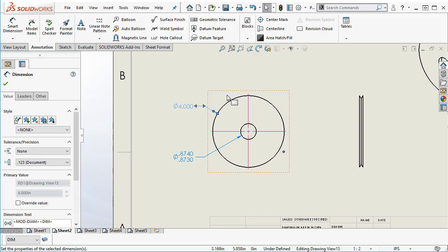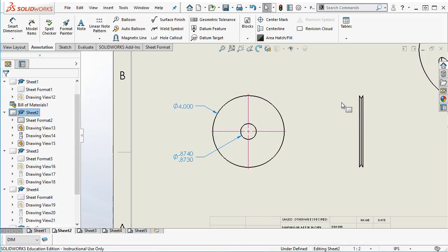In our definition of a datum, it is a feature that we can see, touch, and feel. At least, again, in most cases. There's always exceptions, there's always that one case. But in good practice and beginning, I want something that makes sense. If I'm going to set it on the table and it sits there stable, then this is a primary datum. And so I would pick flatness across this face.